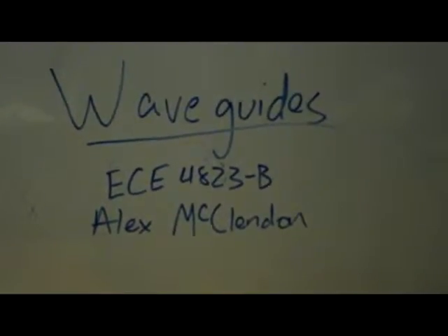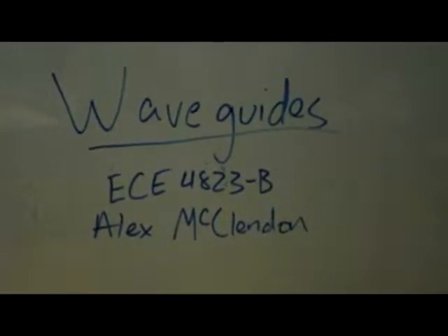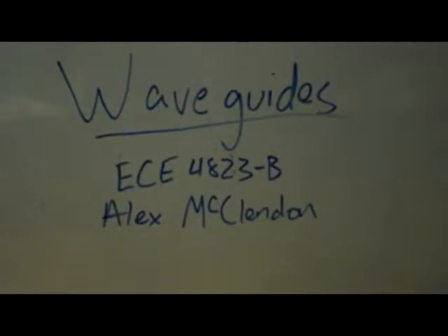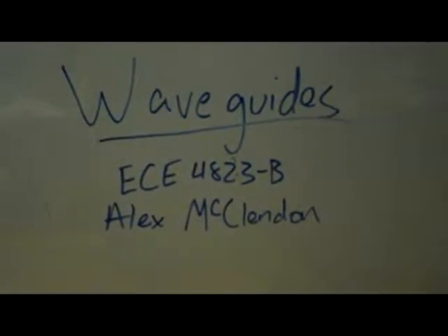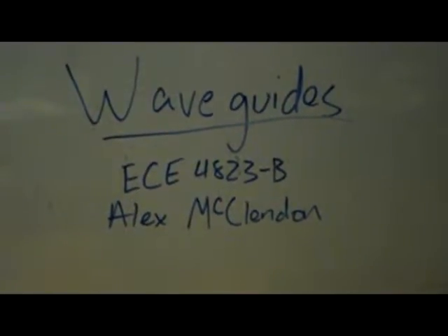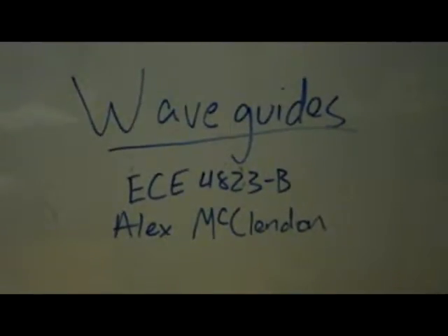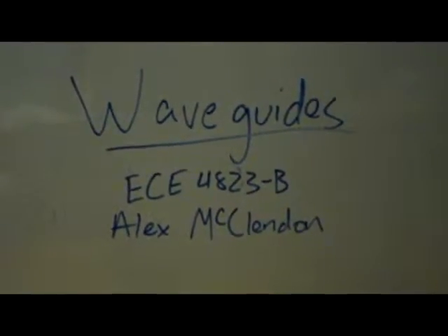At lower frequencies, these are usually pretty good because they're basically lossless. However, at higher frequencies, transmission lines can be quite lossy. Waveguides are very low-loss devices at higher frequencies. So for applications such as satellite communications, waveguides become very important to sustain reliable communication.